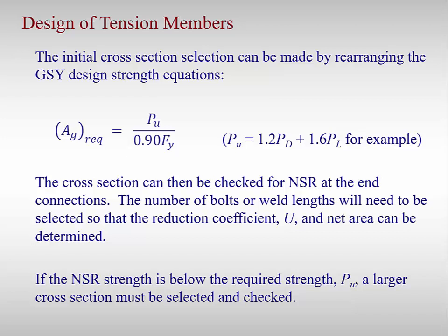The design problem is a little more complicated, as you don't have a member size or dimensions, nor the cross-sectional areas. That is what you're trying to determine. Therefore, you don't know which limit state controls. In the design process, the required member strength is given or the service loads are given, and you must apply the load combinations to find the controlling factored load combination.